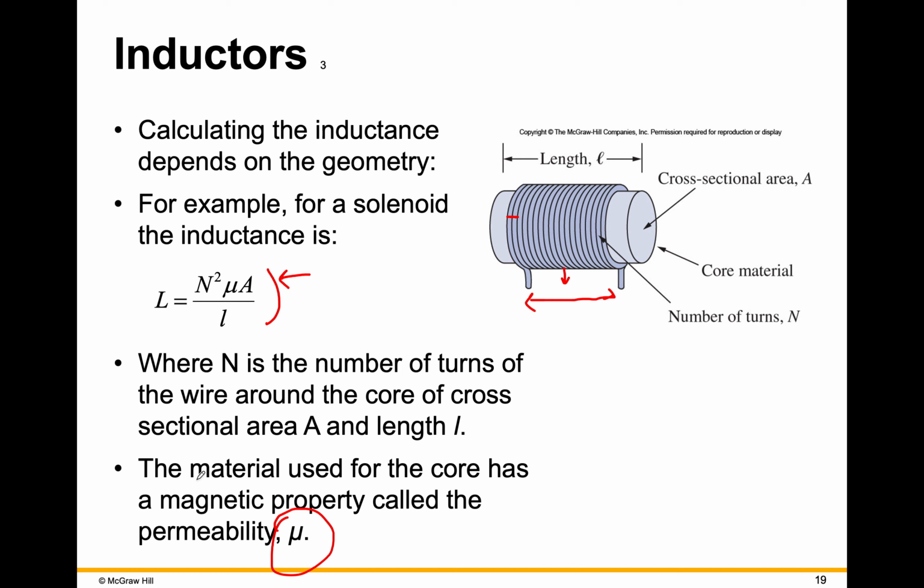The analogous situation in a capacitor is that at the edges of the capacitor you get what is known as a field fringing effect, meaning the electric field is not uniform at the edges. In physics, you generally tend to ignore that. We ignore that a lot in electrical engineering as well, but it is a thing. And so it's what gives you the difference between an inductor or a capacitor built in the real world and one that you model in a circuits class.